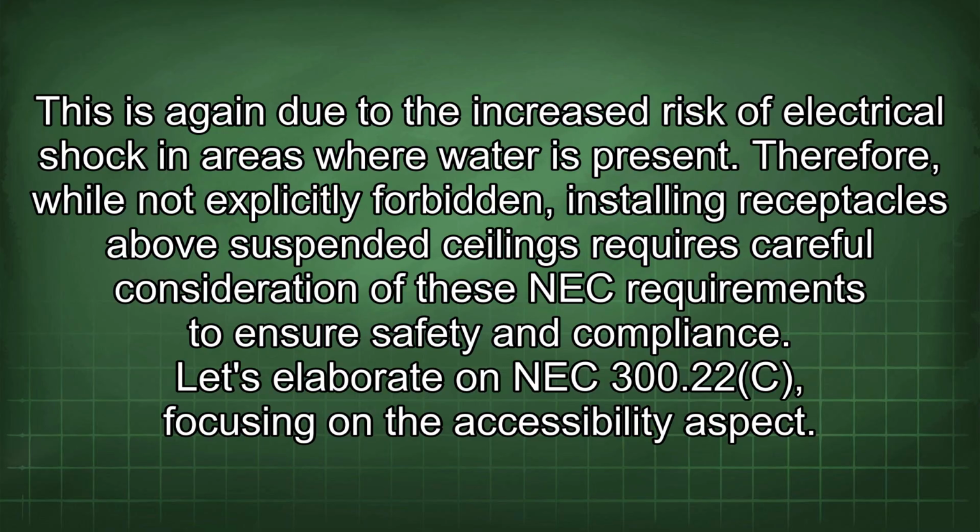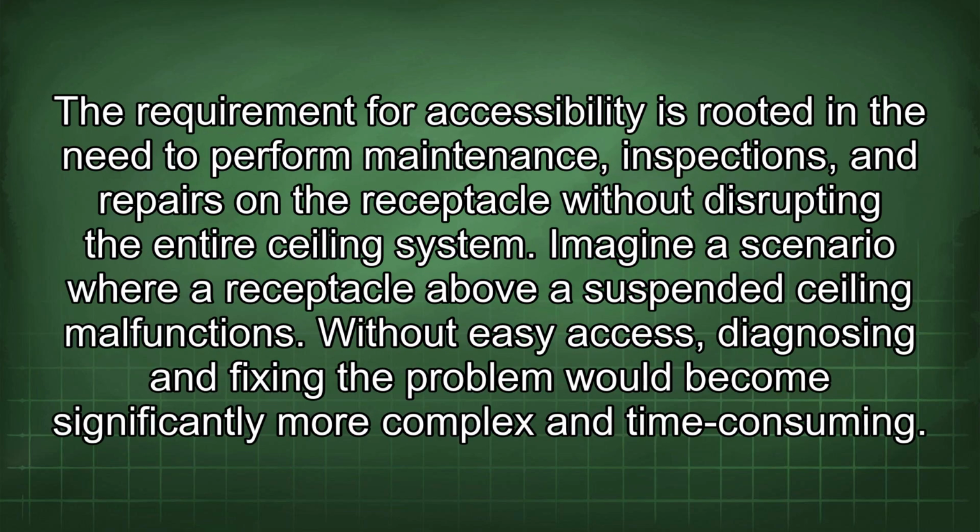Therefore, while not explicitly forbidden, installing receptacles above suspended ceilings requires careful consideration of these NEC requirements to ensure safety and compliance. Let's elaborate on NEC 300.22c, focusing on the accessibility aspect. The requirement for accessibility is rooted in the need to perform maintenance, inspections, and repairs on the receptacle without disrupting the entire ceiling system.